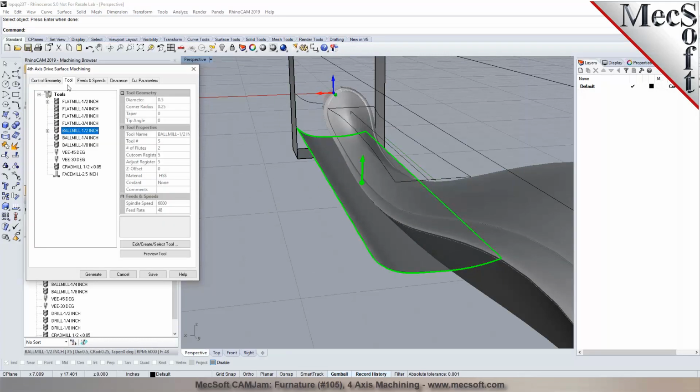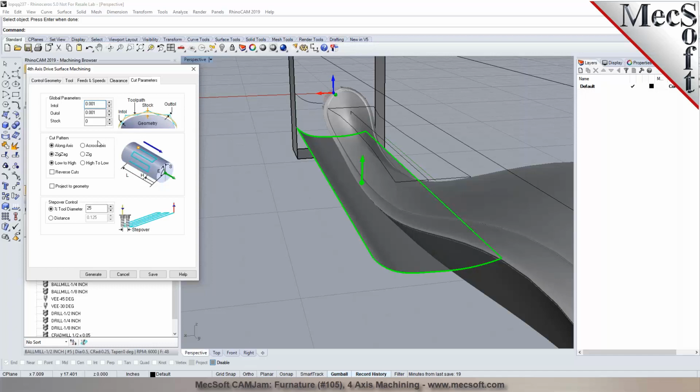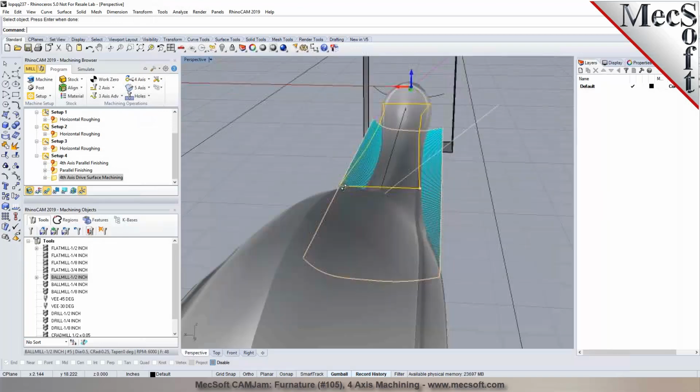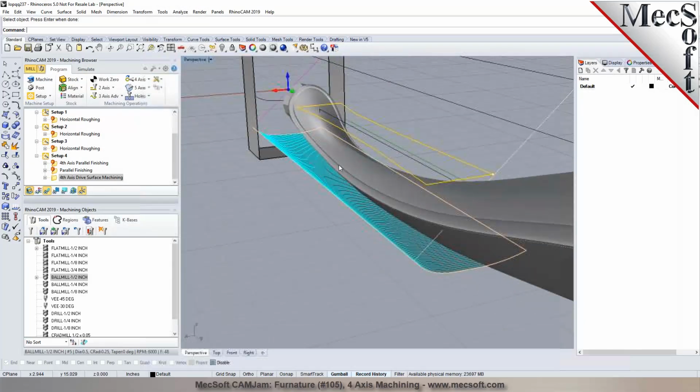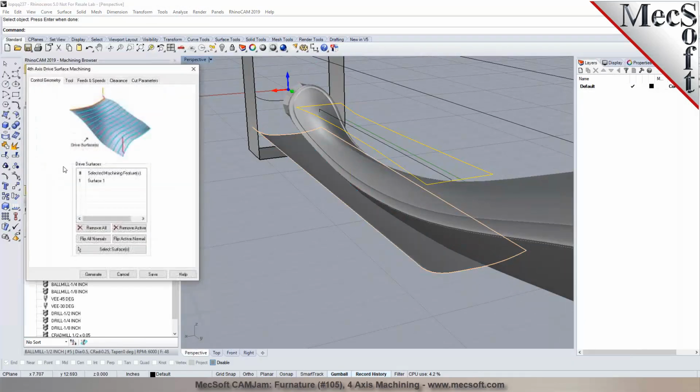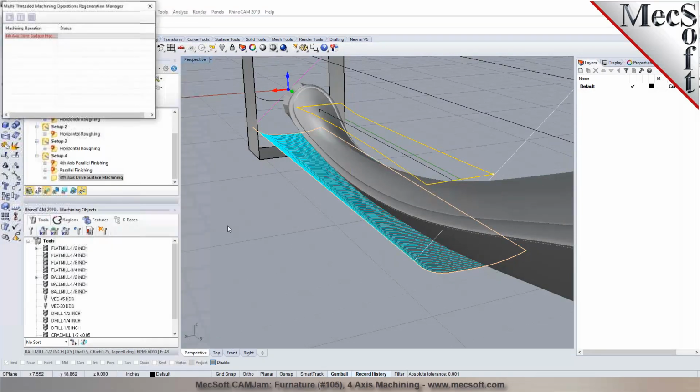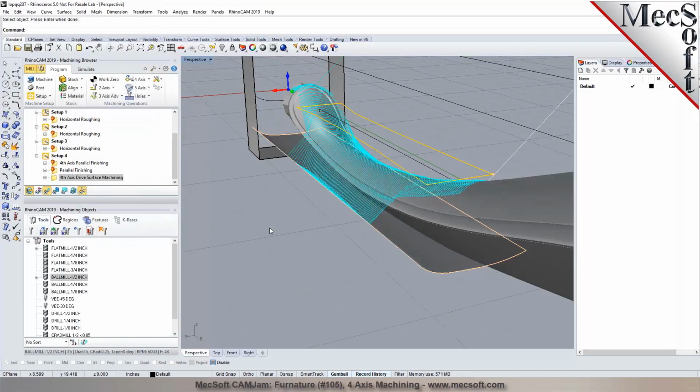If I just pick that surface and then choose a cross axis and generate the toolpath, the toolpath is actually going to be normal to the surface only, as you see it, right? But then I want it to be projected to that model. I'm going to choose project the toolpath to the geometry, so it's going to project the path onto the geometry right there for you.